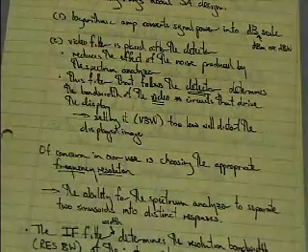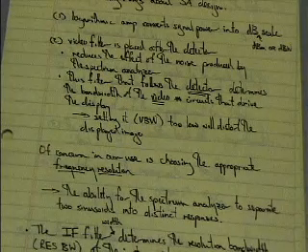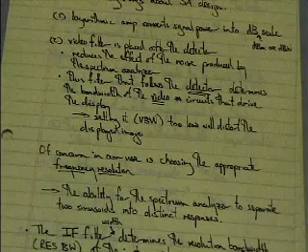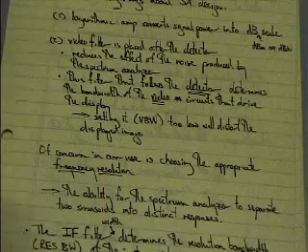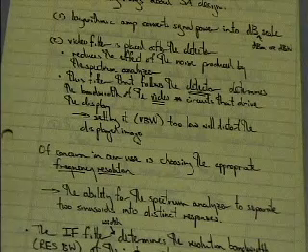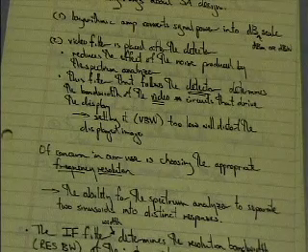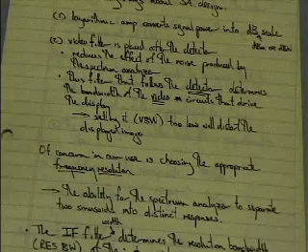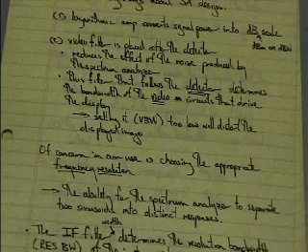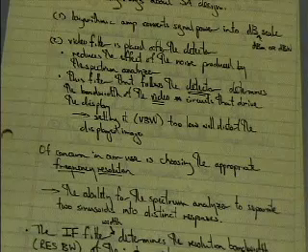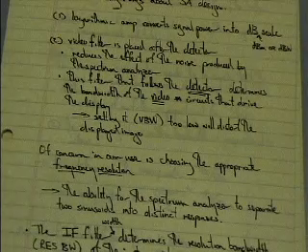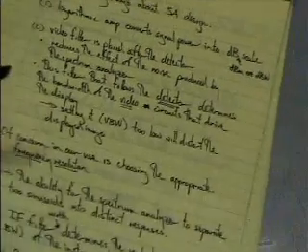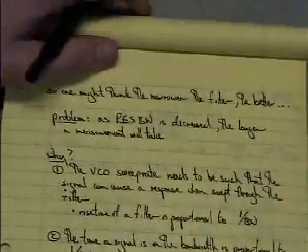The wider the filter is, the more noise is going to come in. So if I make the filter narrower, it's going to let less noise in, reducing my noise floor. That's a good thing. And if I make my filter narrow, I can also distinguish two frequencies which are closer together, and that's also a good thing. So we would think, let's just set the filter as narrow as possible.